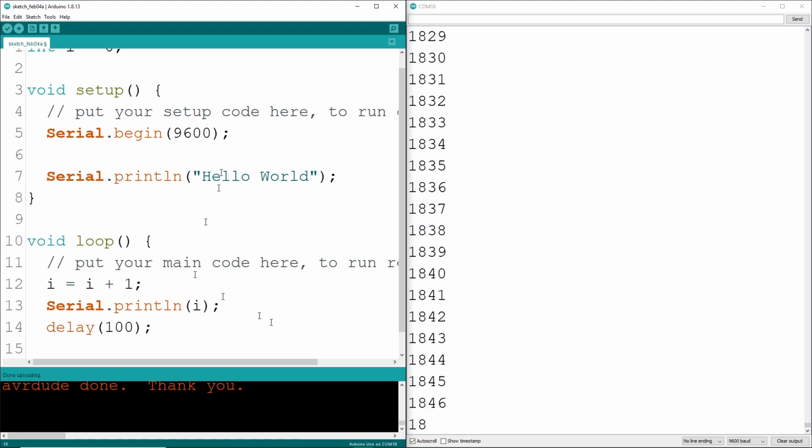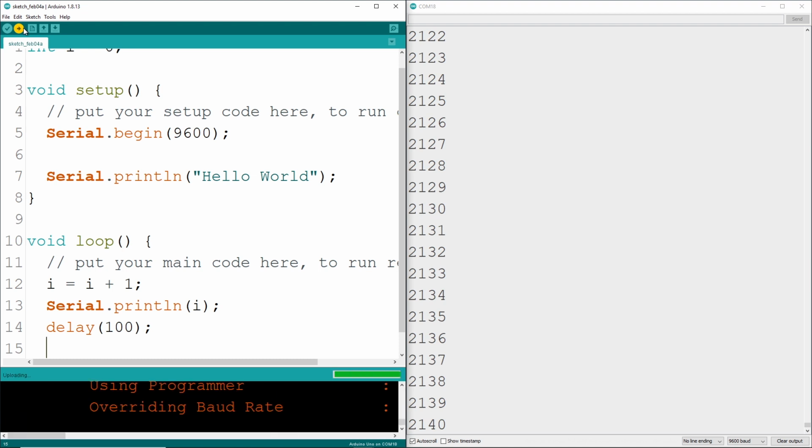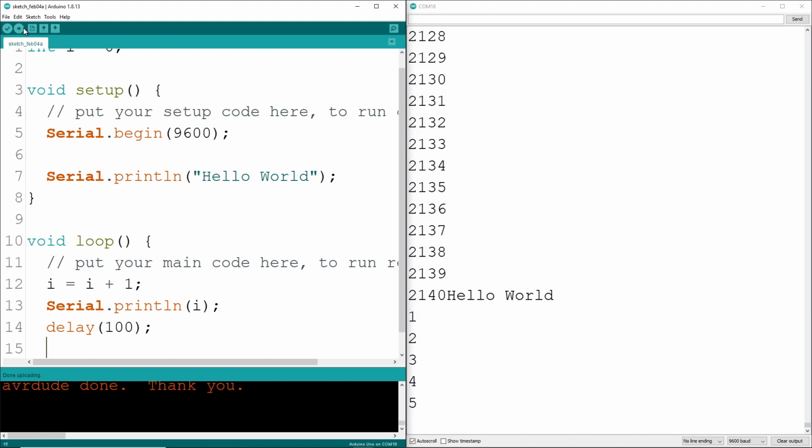The argument is the number of milliseconds you want the processor to wait. How about 1/10 of a second? So we'll enter delay(100). Now you can see the data and actually read the values.